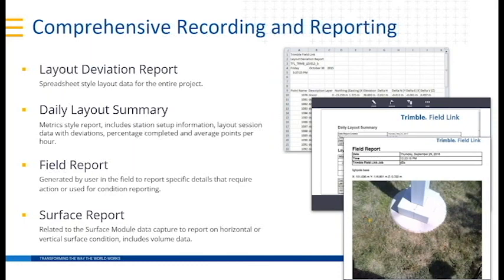We have a field report. So this is something that you want to record out on site. So you record an XYZ coordinate, you can give it a description, you take a picture, it's going to produce a PDF report, push it back up to the cloud, and again, send it on to your team. I think one of the things a lot of our guys that we're working with, I've seen quite a bit now, love this side of the field reporting. But also it's that flexibility. If they're actually communicating with an external party, obviously they can't bring that party into the world of Trimble Connect, but just with the Panasonic on board, connecting it wirelessly to your mobile phone, opening up your email and sending that report over to an external party right there and then, and you haven't left site.